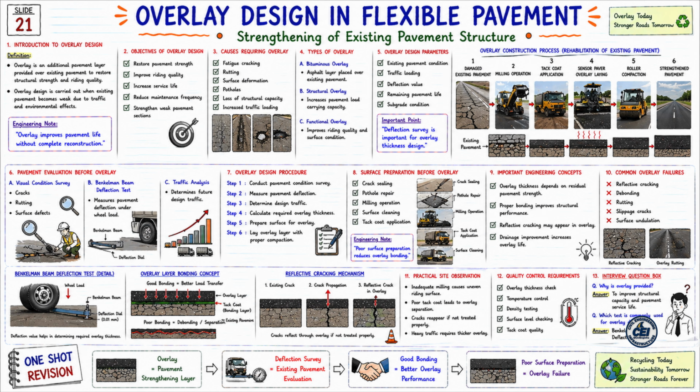Surface preparation before overlay. Proper surface preparation is very important before overlay construction. Crack sealing, pothole repair, surface cleaning, milling of damaged layer, tack coat application. Now see the engineering note below. Proper surface preparation ensures strong bonding. And strong bonding is the most important factor for overlay performance.